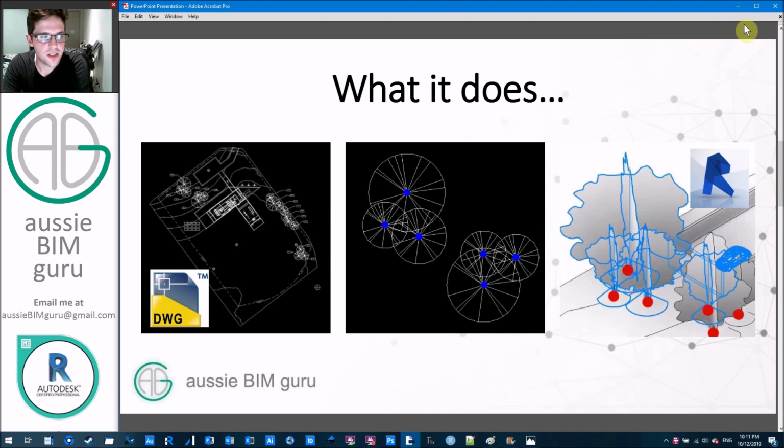So essentially we're going to take the Revit sample project, we're going to export a DWG with the trees as blocks as well. We're going to delete all the trees because we're going crazy like that. And then we're going to insert the CAD link and we're going to place families based on the block names and the positions of the blocks.